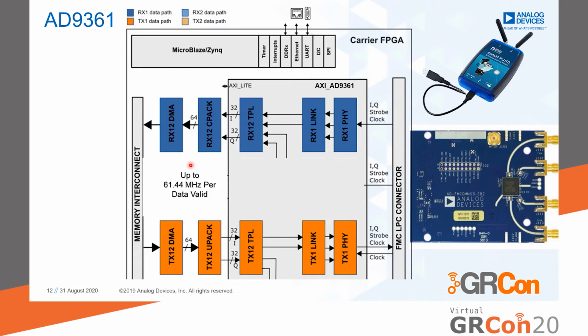So in LVDS mode, the main clock inside the system will actually run at 4x the data rate. So this will be up at technically around 250, but you'll only get a sample every 4 clock cycles. In CMOS mode, like how Pluto is configured, you get 1 sample per clock cycle.